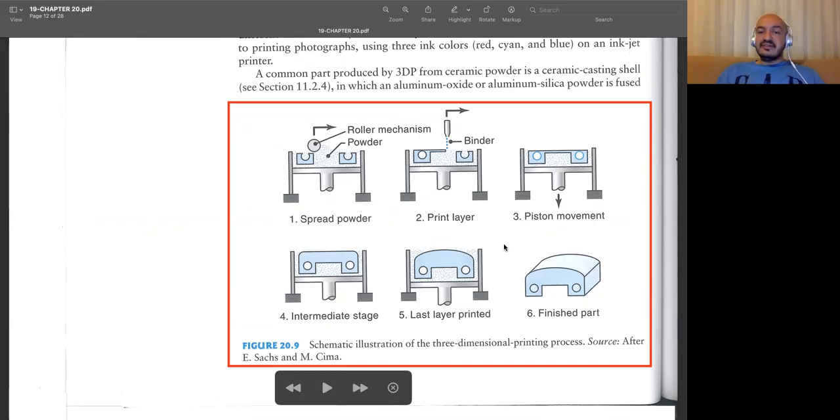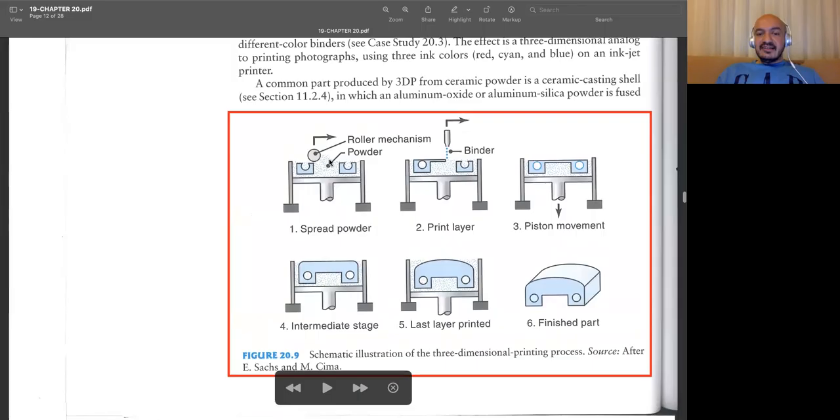You can even start manufacturing the same machine on your own. So what are the differences? This time, again, we are using a powder bed, but the difference is that instead of a laser, we are using a kind of a head, and it's depositing binders. You see, binders are deposited onto the table, and with the help of it, the powders are fused together, joined together, but the rest is the same.